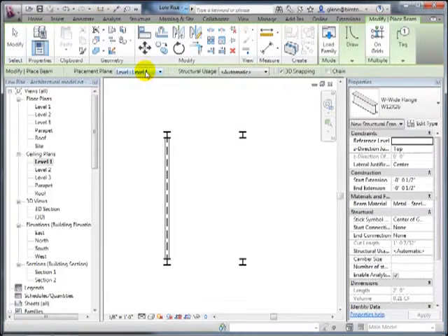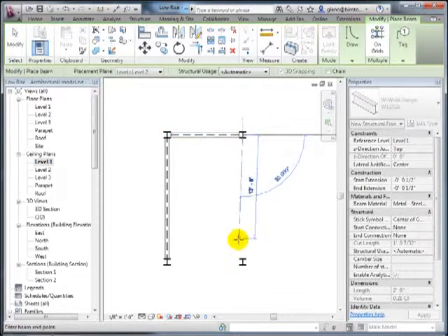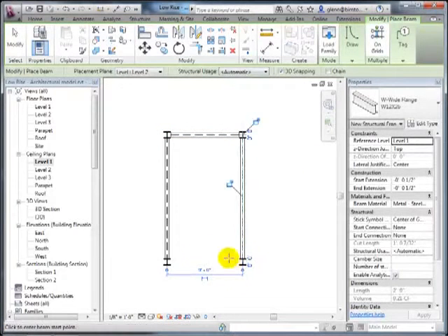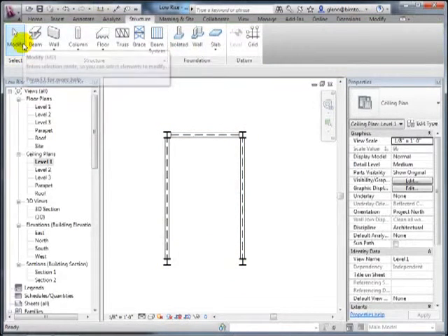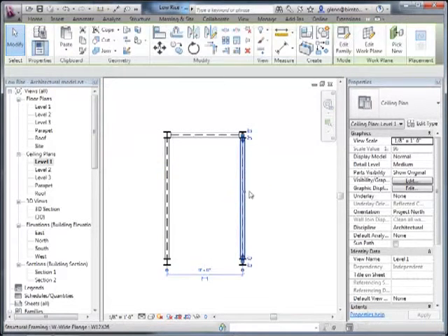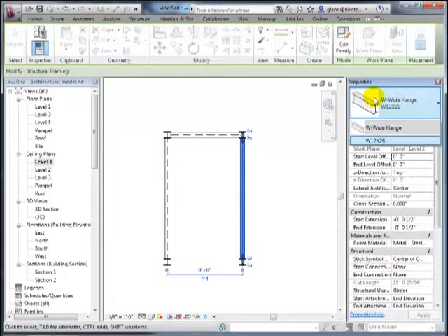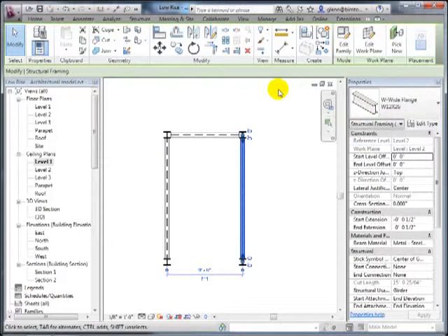Okay, in a 2D view, you have to be careful about what level you place it at, whether I'm going to place it at level 1 or place it at level 2. But now I can go through and do that same sort of snapping. Now, I'm not paying any attention to the size of these beams right now. That's kind of okay, because a way we often do this is we'll place beams based on some that are available in here, and we probably have an intuitive notion about how big that beam may be based on our understanding of what the span is and our experience.